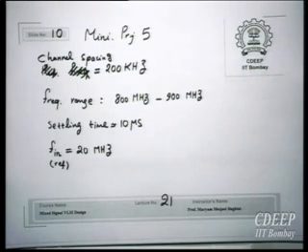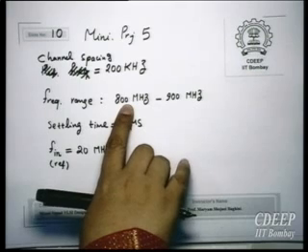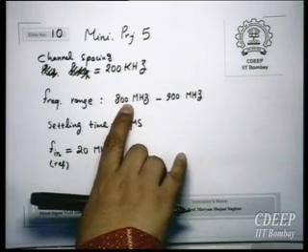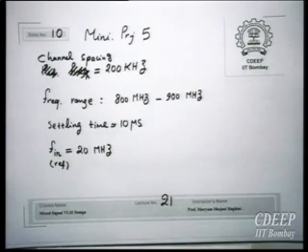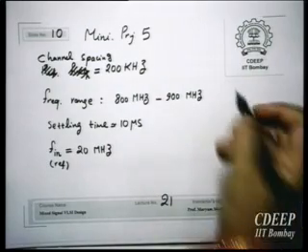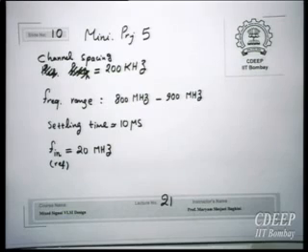One more thing is the divider. Right now, I didn't get time to talk about the prescaler and how to make the ratio. So right now, you can just use a simple counter. Therefore, if the divider ratio doesn't come out correctly, you can adjust this frequency a little. This frequency is controlled by the counter.